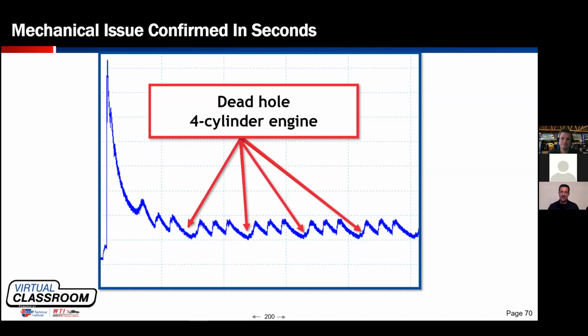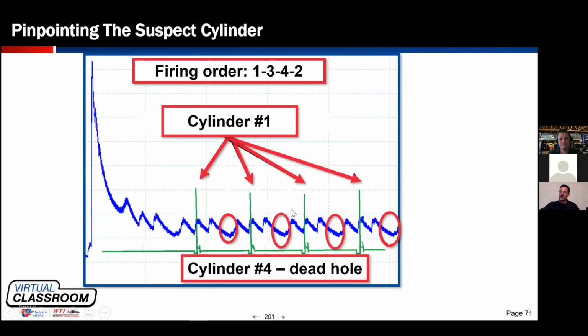Please don't make the same mistake others have made in the past. Unless you are 100% sure of the firing order, please do not guess. It's not worth skipping over the invested time to research it. If you're wrong, you are taking the wrong cylinder head off the car. I've seen it, believe me. So don't guess. At this point, I know I have to grab an ignition sync, because right now the only information on the screen regarding engine health is that one of the four cylinders is not contributing like the other three. Now it's time to find out which.